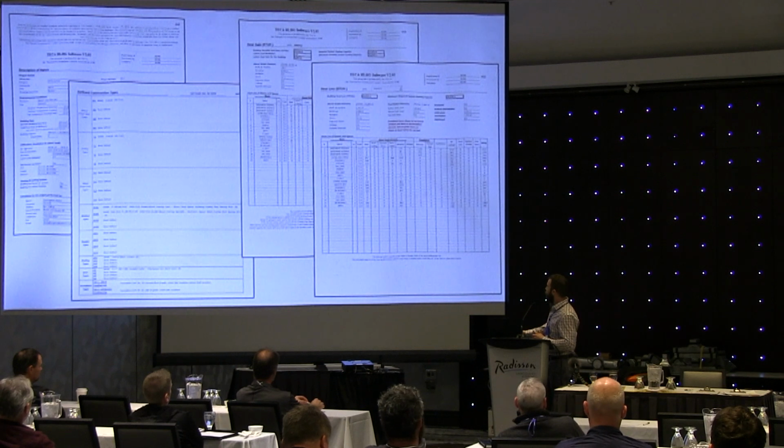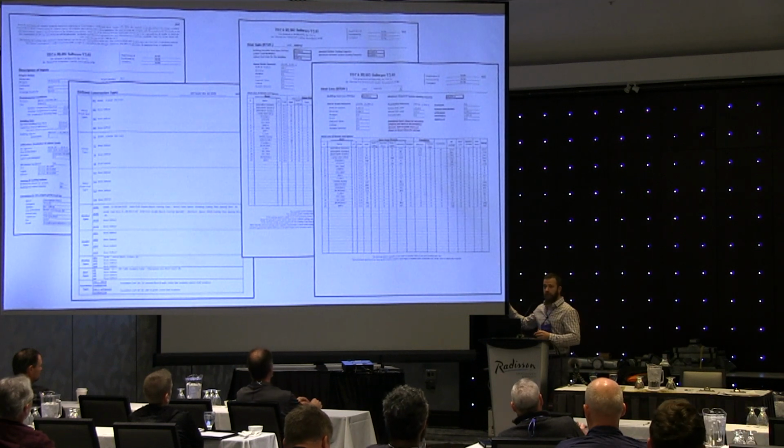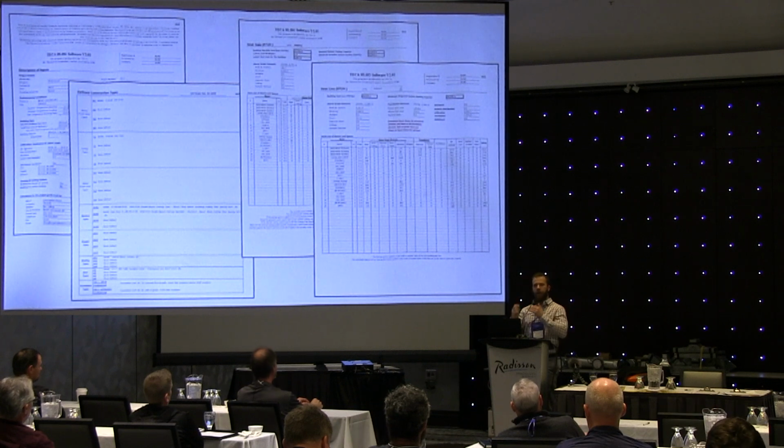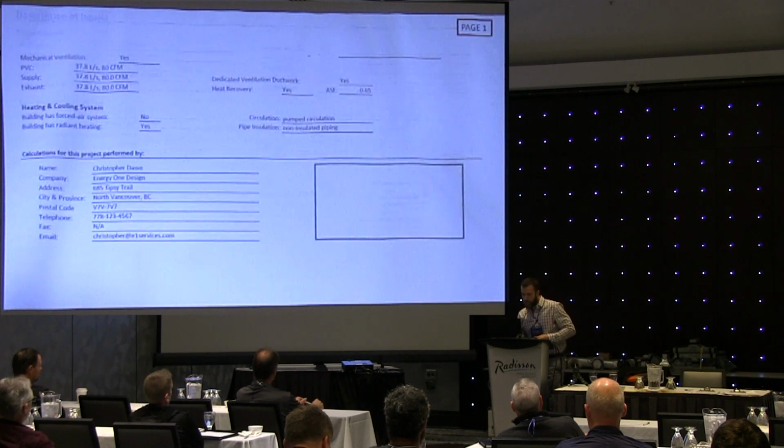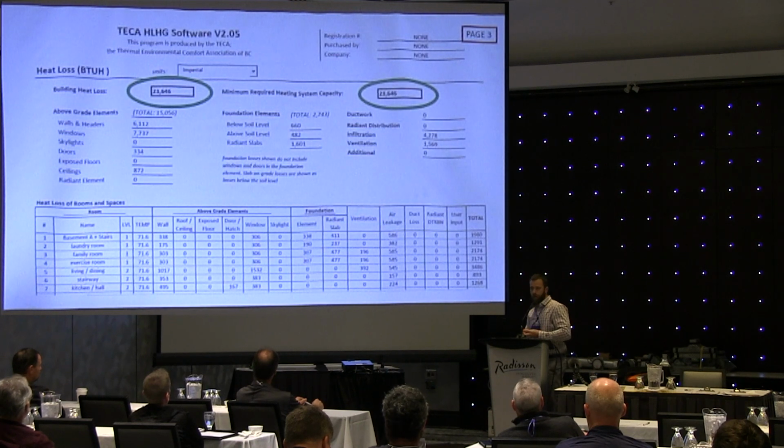Lastly, what you could do is look at the heat loss and heat gain values. You just follow down. Heat loss looks really high. So then you look at these different components. Down here, I'm not sure if you guys can see this, but walls and headers, windows, skylights, doors. My heat loss is really high. Let's look at this. Wow, windows is ten times what anything else is. That seems strange to me.